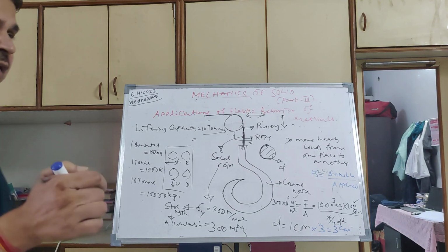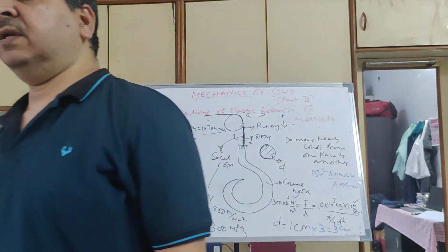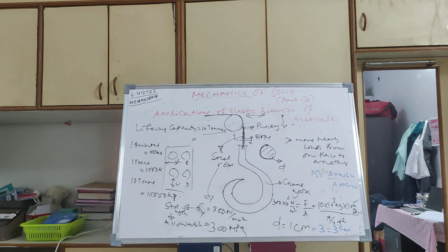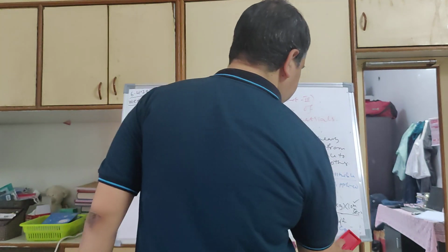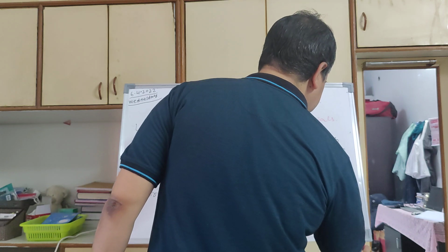So rather than using a single rod of this diameter, it is better to use smaller wires, braid them, and convert them into a rope, and that rope will have a diameter of 3 cm or whatever, instead of using one wire of 3. Actually here it is not exactly 3 cm. A factor of safety of 3 does not mean that it is 3 cm.